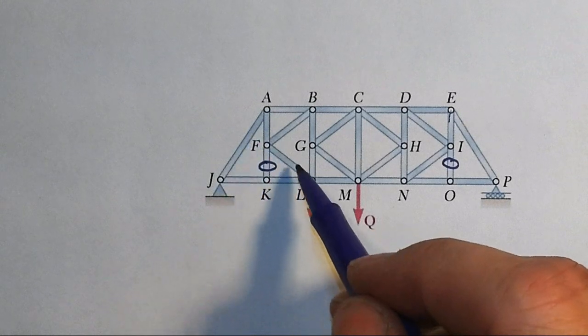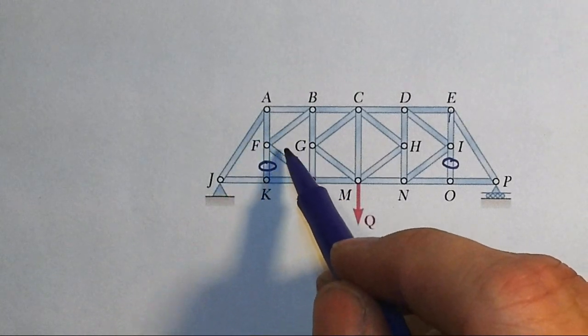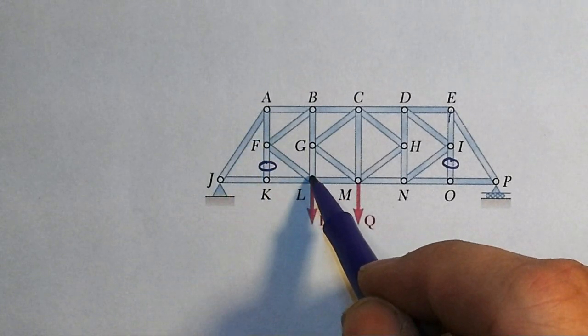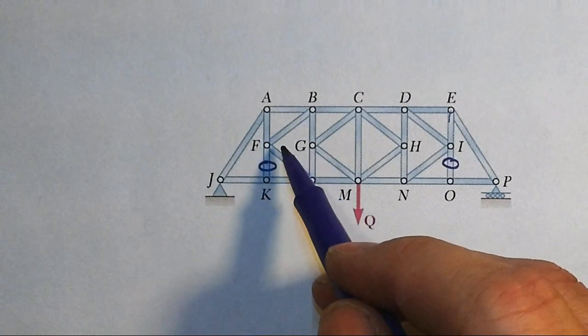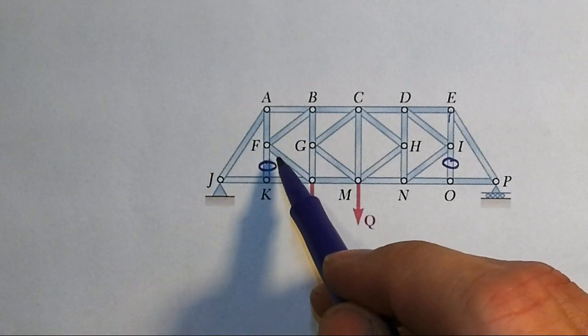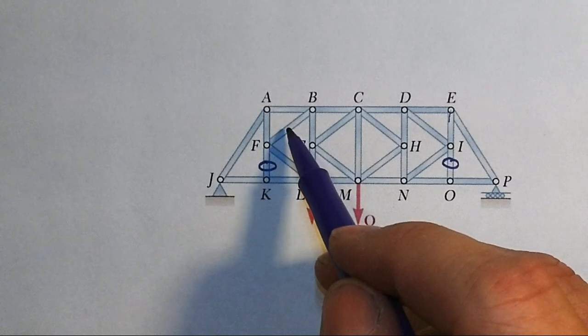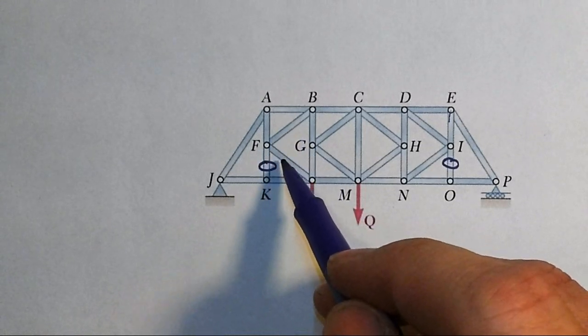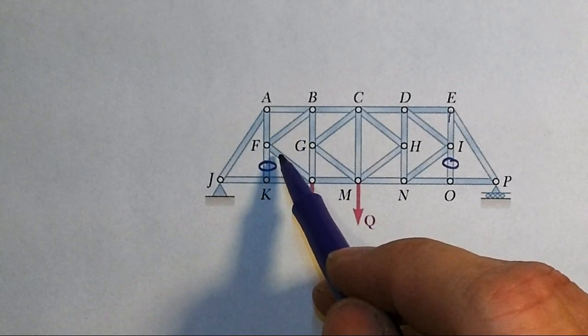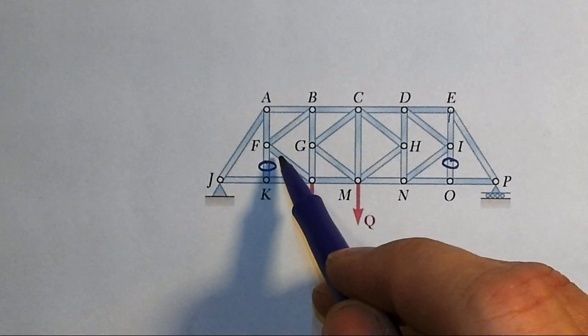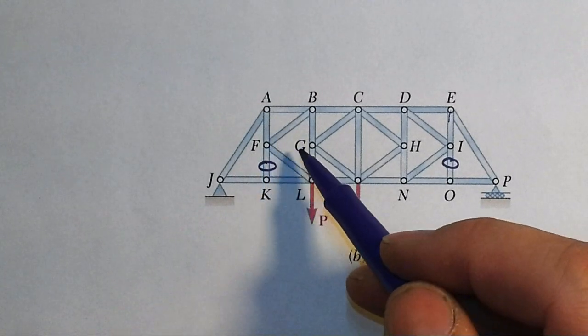Now, if we were to decide that one of these diagonals was somehow 0, then maybe we'd follow the ripple effect. But whatever the X component of BF is, FL has to have an equal opposite. So that means one's in tension, one's in compression, in order for that to work out in the X direction.